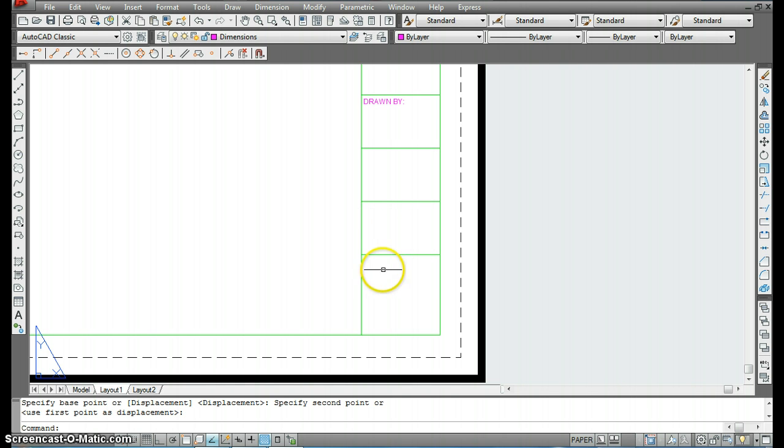And then lastly at the bottom, you're going to put sheet in the upper corner at a 0.05 height, and then in a much larger height, we can just put 1:1, and of course those will change as we go, and that'll be all that we add in our title block. Once you're done with that, just pause for a minute and I will show you exactly how I want you to save that, but I'll leave that for telling you in person.